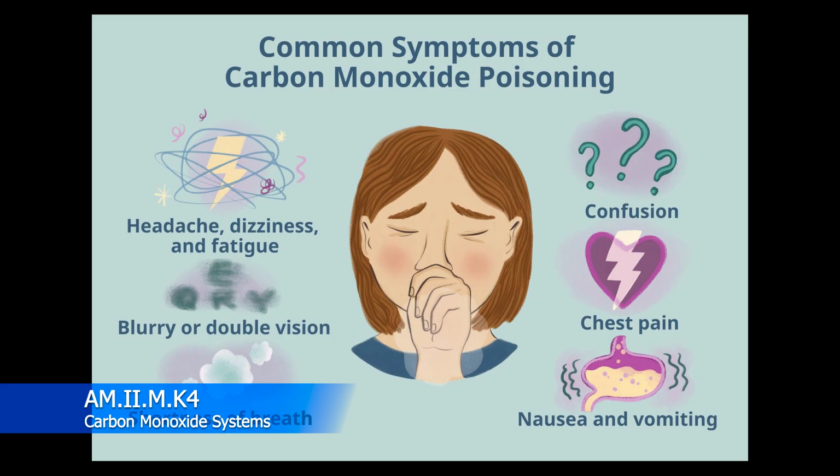This is super dangerous. When you start working on, especially GA airplanes, there's constant attention being paid to the exhaust system on aircraft because a lot of people have died from carbon monoxide poisoning. One of the things that you'll do is every annual you'll take a little carbon monoxide card out of the airplane and put a new one in. They're super cheap, and all they do is change colors. They'll get black if they're exposed to carbon monoxide, so that way they let the pilot and the passengers know, hey, there's carbon monoxide present inside of the cabin. You need to do something about it. That's the why behind it.